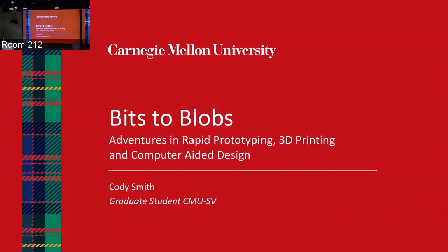Cody, I have one. What are the factors governing the speed of the printing? That's a good question. So in S3D, you can set the XY travel. And if you set it too high, at some point you start asking the machine to do something it just can't do. So I believe I was printing at 1600 or 1700 millimeters per minute or something like that. There's going to be a point where it's fast and it's consistent, and that's where you're going to stop. And so, building machines with gantries that have linear motion that can go faster, sure.